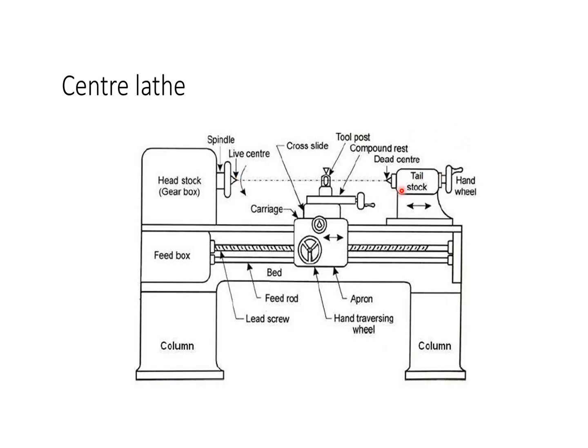Then the tailstock. The tailstock can be used to support the end of workpiece with a center to support longer blanks or to hold tools for drilling, reaming, threading, or cutting tapers. Also, it can be adjusted in position along the ways to accommodate different length workpieces. The tailstock barrel can be fed along the axis of rotation with the tailstock handwheel.